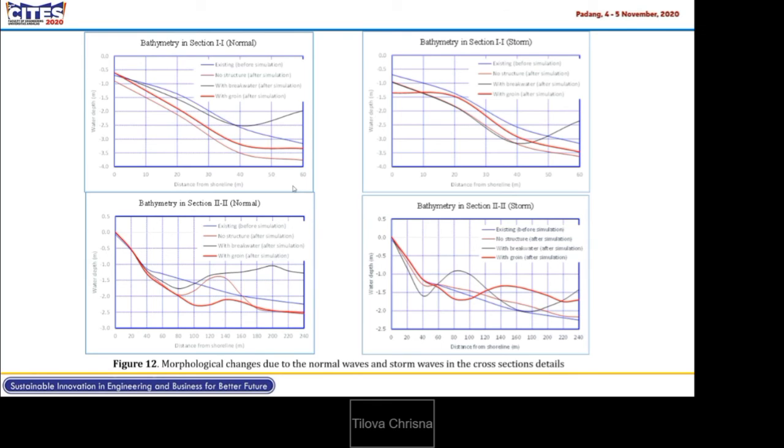In normal wave condition, breakwaters give the best result as shore protection because in normal wave, sediment transport is influenced mostly by wave and then current. But in stormy wave condition, the simulation showed an anomaly: during a storm, the wave height and its energy towards the shore decrease because some of the waves have broken further from the shoreline. Current forces at very high speed are the dominant cause of the erosion process along the near shore. So in stormy wave, the role of groynes is more dominant than the breakwater because groynes function well to hold sediment transport along the near shore.